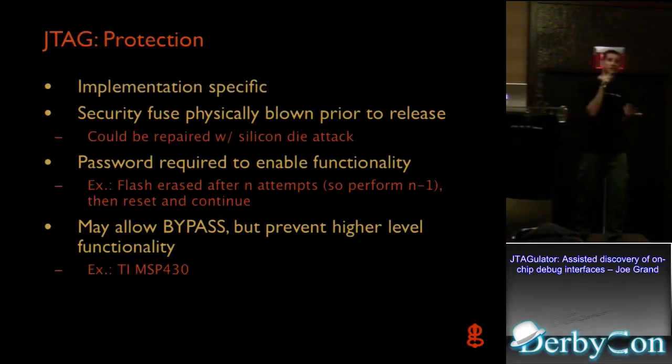Some devices do have password protection, where you have to send some sort of password into some register in the TAP, some custom addition that a vendor has put in there. One example that somebody had told me once was they had a microcontroller with internal flash, that after some number of invalid password attempts, the flash would be erased. But there was no non-volatile flag, right? So you could try it n-1 times, and if you didn't get it, you reset the device, and it would reset the counter, and you could sort of brute force it that way.